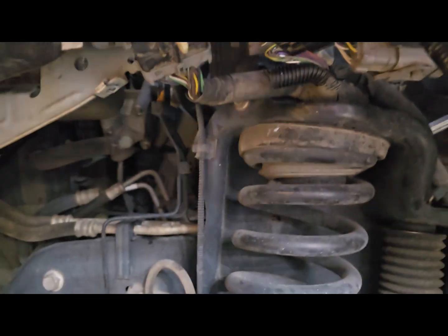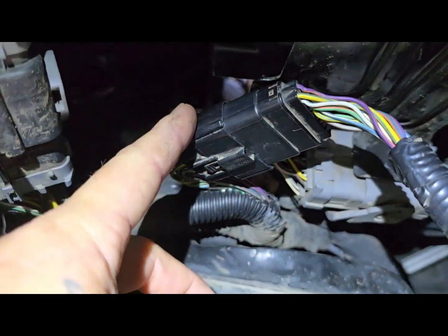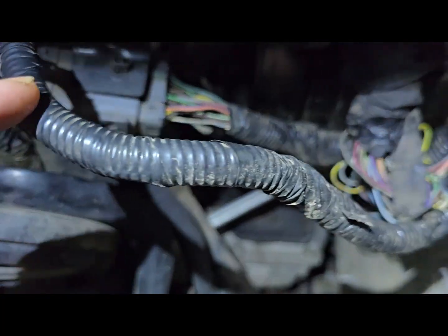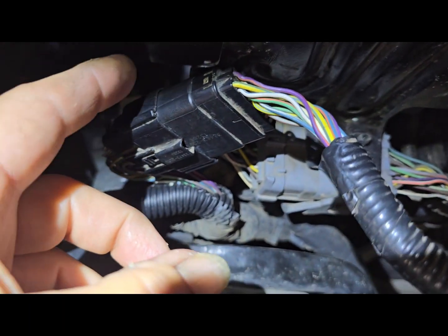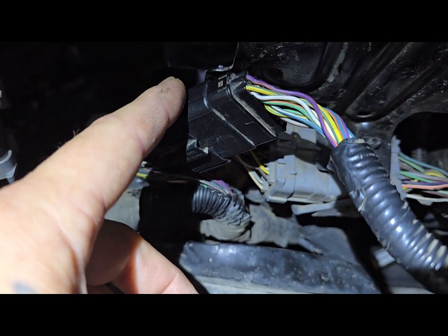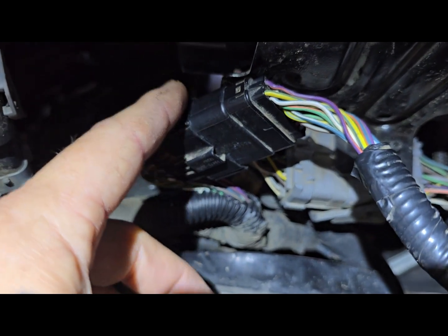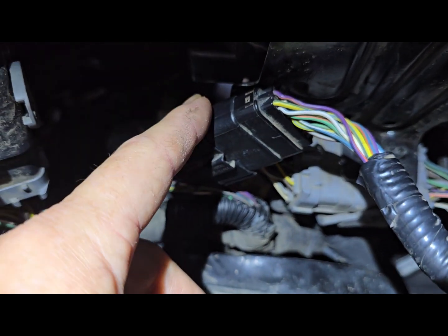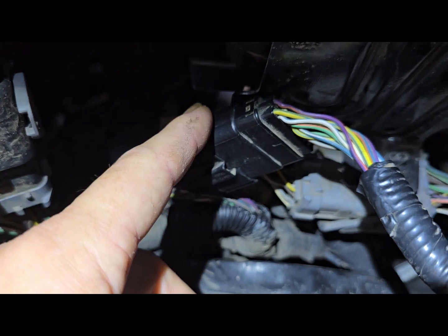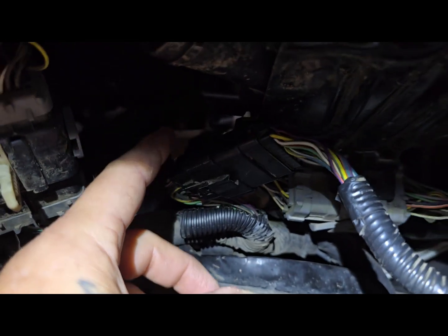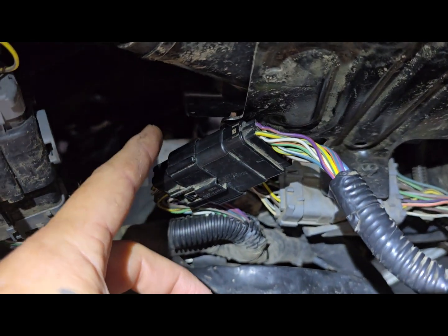Now, one thing I need to look into is this connector right here. The customer did a bunch of troubleshooting, you can see he cut open a whole bunch of wiring. And if he slightly disconnects this connector, just pulls it back just a little bit, he actually has shifting. He can shift normal. He doesn't have a lack of power. With this connected, lack of power, and when I put this thing in gear, it clunks and grunts and groans and barely moves.